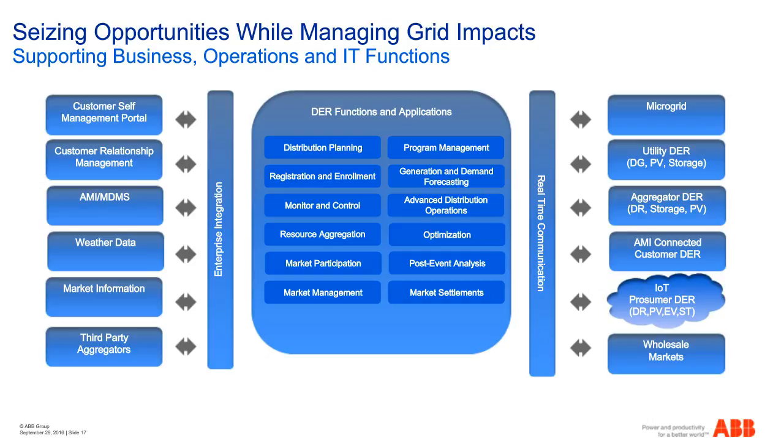This covers both long-term build-out of infrastructure to support DER as well as short-term planning to accommodate installation at specific customer sites. There are popular desktop applications for performing this process. This process requires assessing the capacity of the local grid to absorb the DER and assessing the current condition of the affected substation and feeders, assessing the potential for reverse power flow, risk to neighboring customers of either increased voltage or frequency variation, and increased cost of wear and tear on utility assets. This may result in the need for additional or updated breakers, switchgear, or increased transformer capacity.